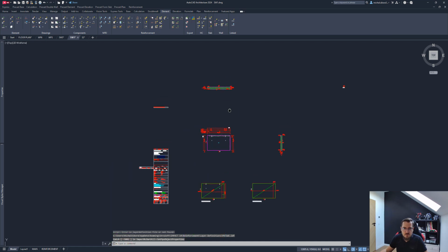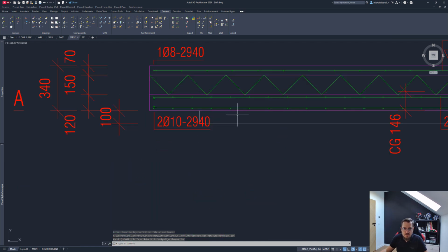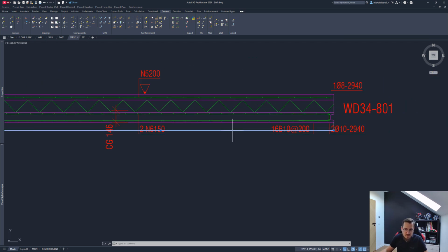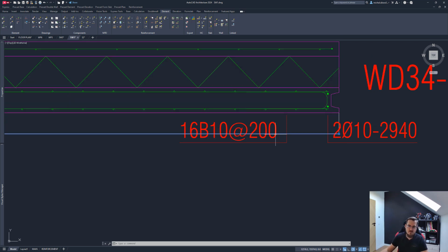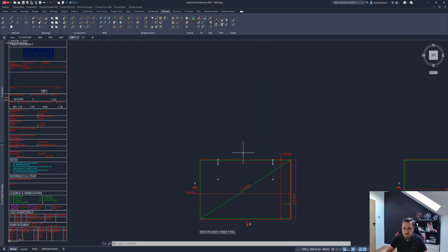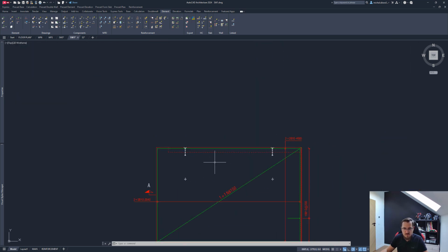All right, so the drawing was recreated, and you can see the thickening has been changed, right? Just a matter of now, the thickening is not automatically detected, so basically the dimensions don't automatically detect that there's a thickening there. So the dimensions you have to move away by hand, but as long as most of the work is done for you, it's all good. So let us do that reinforcement.